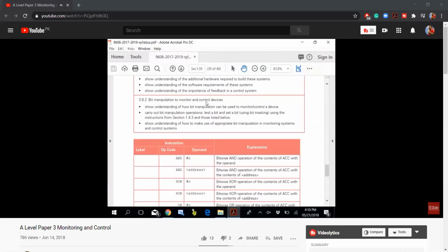We were given this task to connect all these machines using RJ45, these LAN wires, cables, and to record it all automatically. Every machine had a manual given with it, and that manual tells how to contact that machine, how to send a pattern of bits to that machine so that machine could understand what data is being asked, and it returns the data. Then you have to catch that data back and report it on a screen or store it, whatever.